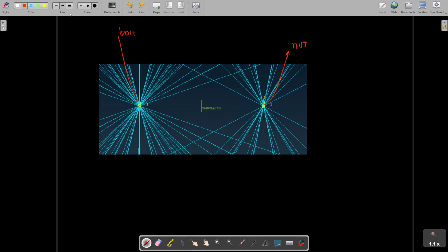So what I usually do is to always define the x-axis from node 1 to node 2, so that I know that if I apply a positive connector load, I'm going to try to perform this kind of movement. So what I'm going to actually need to do is to apply a negative connector load.